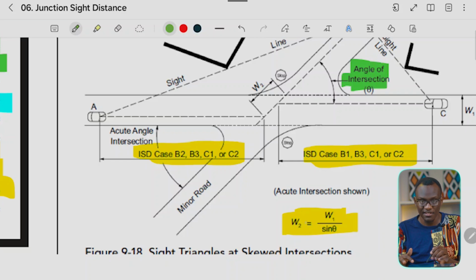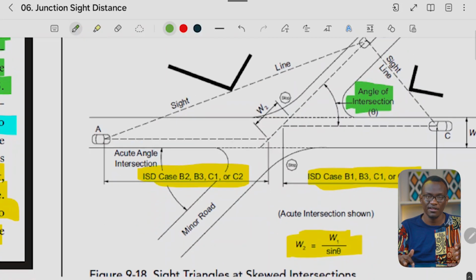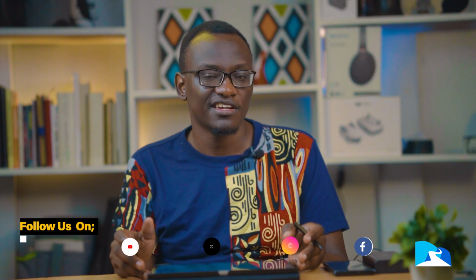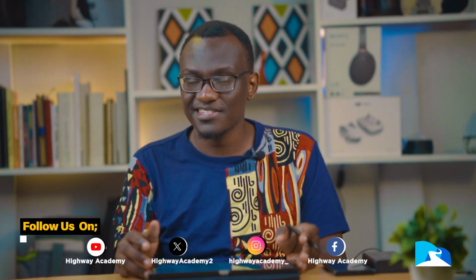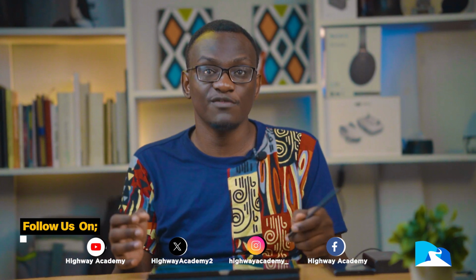sight distance because we have to establish the sight line. Okay, you need this, and so you can see how much farther back. So when your junction is skewed, you need further sight distance, which may not be the wisest. So when you're designing these junctions, make sure you keep to 90 degrees. Worst case, 75 degrees.